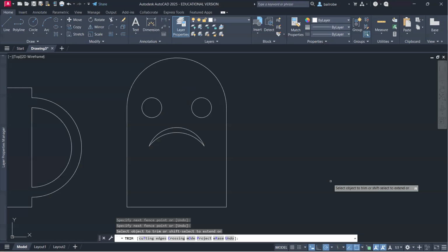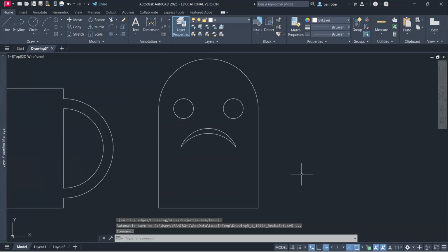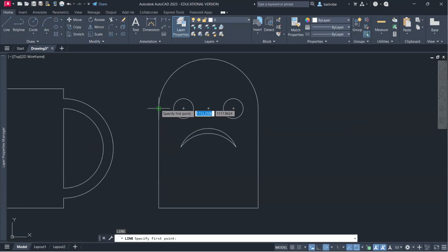Okay. So, the frown, yep. Well, question about the offset 500. So you said it has a line on the top, right? Yeah, I added the line back. So I enter offset 500. I select the object. Instead of selecting a line, I select the whole square. Yeah, because it used to be a rectangle. So that's okay. What you can do is maybe you can delete that top line, trim, and then make a new line.